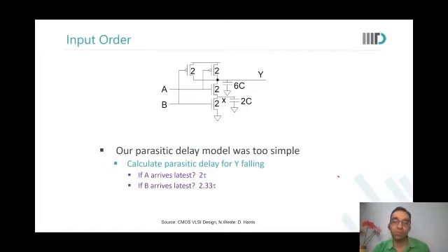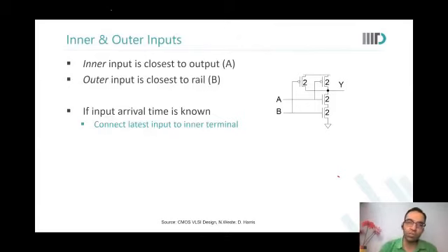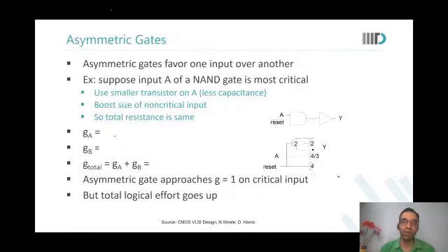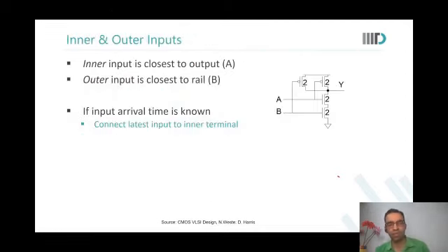Yes. What I'm saying, Ranjit, is that even in a simple two input NAND gate, the input which is closer to the output should be the one that is arriving late. Even in a simple circuit like a NAND gate, order matters. In a complex circuit, you're absolutely right. Bang on. Order definitely matters. All of us understand why it matters? Any questions around that, please?